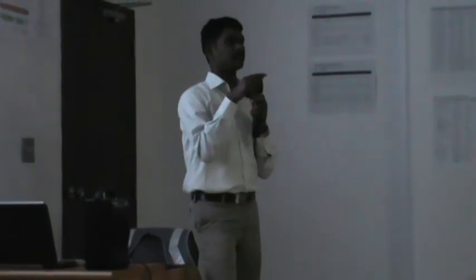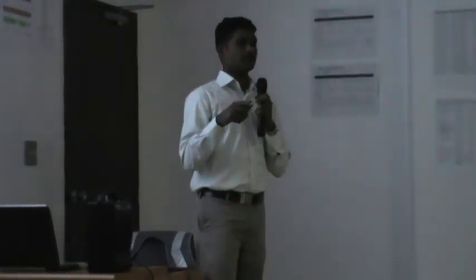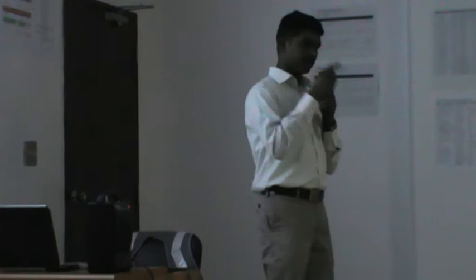Here we use the concept DTM and FDT. So what you can do, the calibration of the field instrument can be done in the DCS also. You no need to go and do the calibration from the field. Like your valve, here normally for the whole plant, we use the ABB positioner. That positioner can be calibrated from the field. Sorry, it is possible in the field, but the advantage is that in the DCS also you can calibrate.